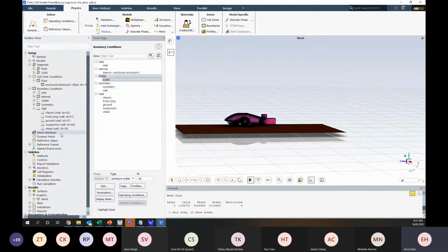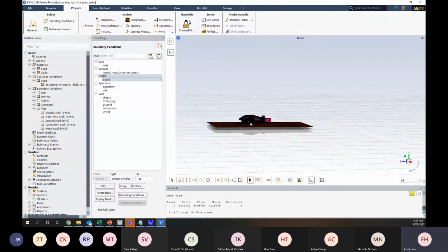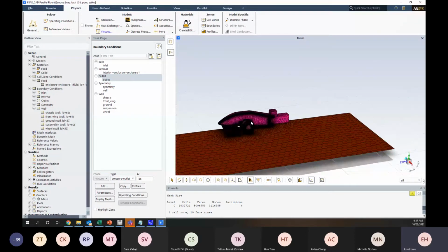How do you calibrate the turbulence values? That's a really difficult question. Well, it's not a difficult question. It's a simple question, but it's very case specific. So if you have a wind tunnel run and you're matching your values in your wind tunnel, you'd probably have a really low turbulence specification, but you might tune that turbulence specification to get the right values out. So if everything else matches what's happening in the wind tunnel, and generally we want a turbulent intensity of around 1%, but the force values aren't quite matching, you can calibrate that turbulent intensity to suit.